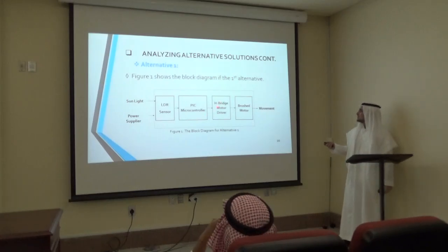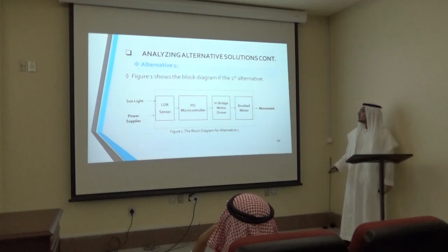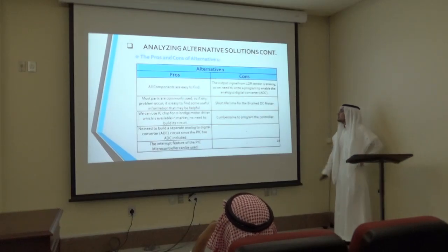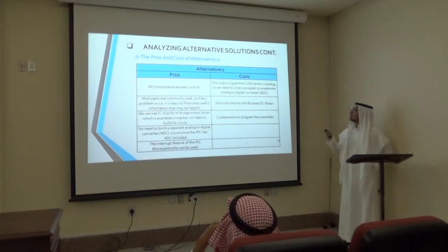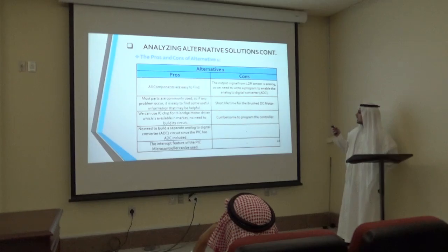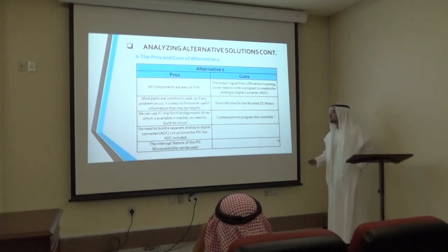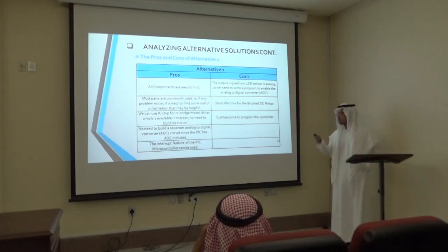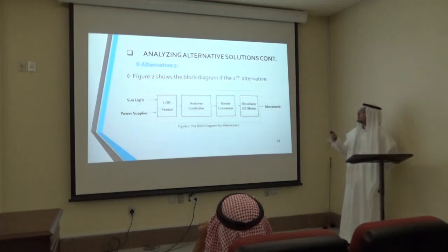The H-bridge will understand and modify the signal and let the brush motor operate in the desired direction. As you can see, these are the pros and cons of alternative number 1. The main problem that we have in this design is the PIC controller is a little more difficult to program than Arduino. So let's go to the second alternative.